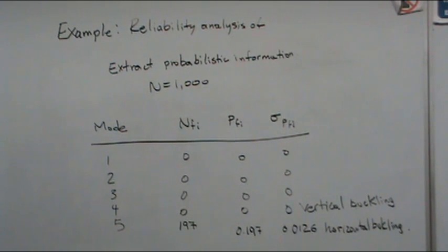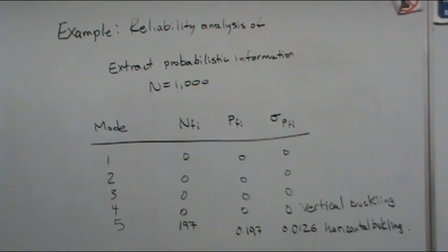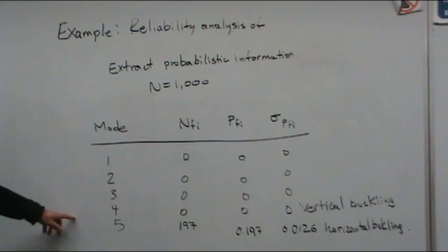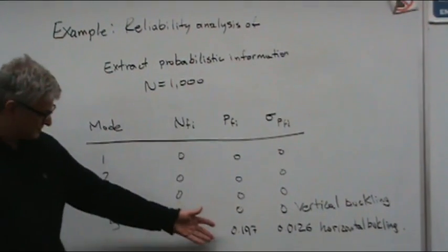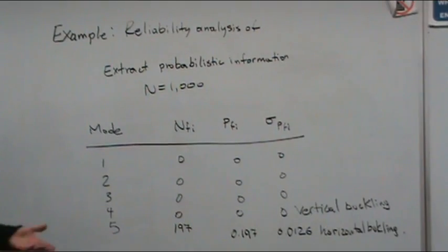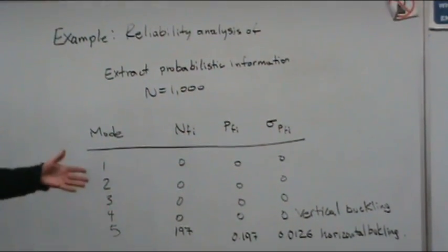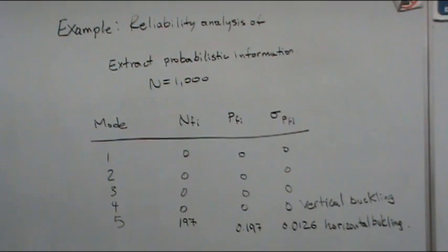And so you got to do something with the flanges. That's the problem. Now, does it make sense to do more Monte Carlo simulations when you reach this point? No, because you know that this design is unacceptable anyway. It doesn't matter if the probability of failure is 20% or maybe 15% or 25%. Doesn't matter. What you have to do is stop here and reinforce the design. That's the conclusion.